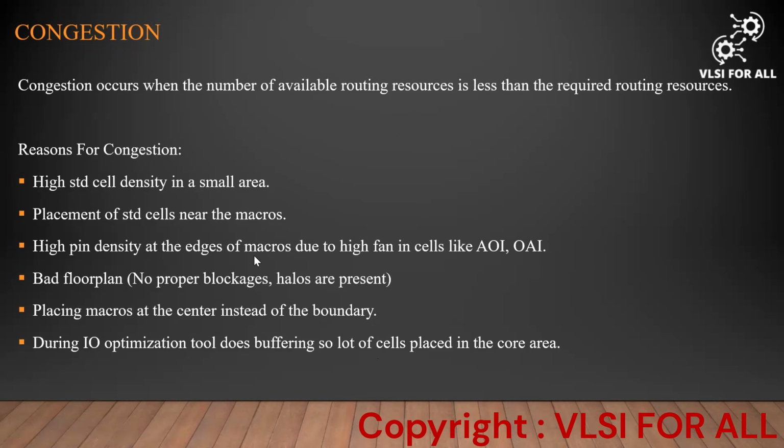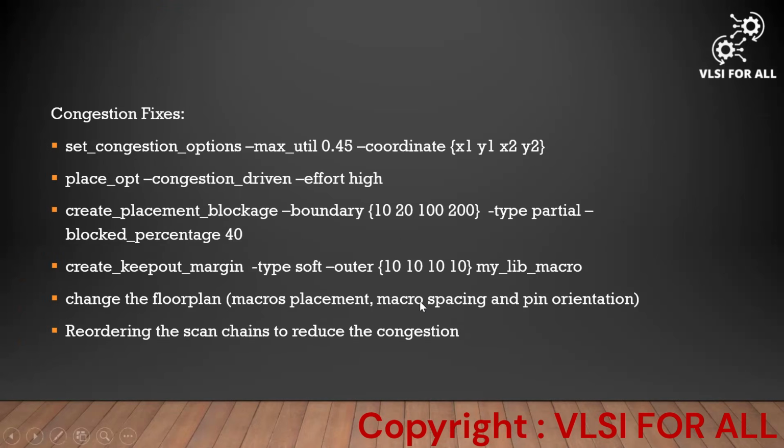So while it adds buffers, there are a lot of cells in our core area. So it may cause congestion, and it also causes power issues. So these are all the reasons for congestion. How we have to fix it if we see some congestion, we'll discuss. Sorry. So, congestion fix techniques.